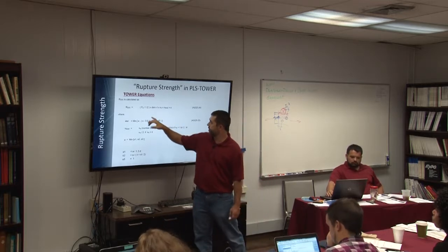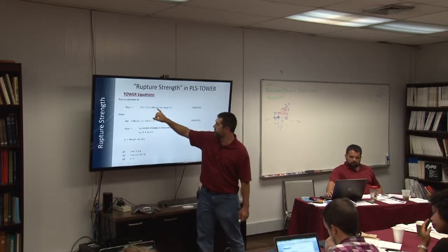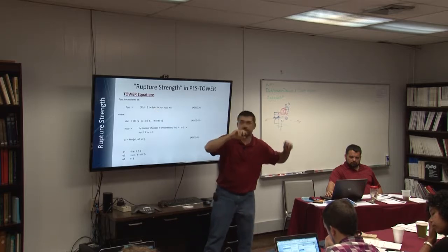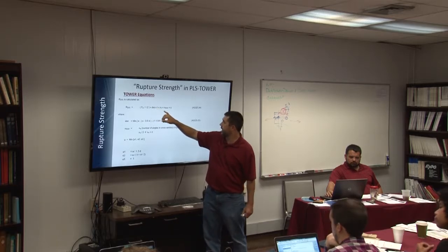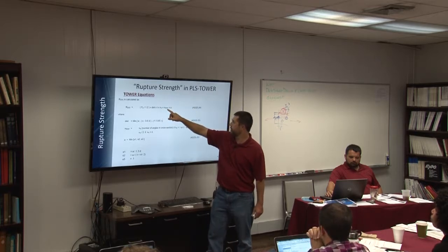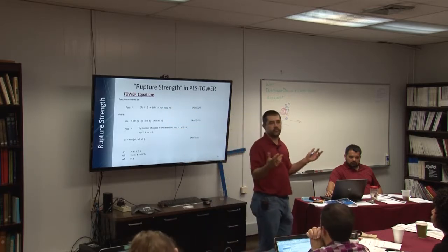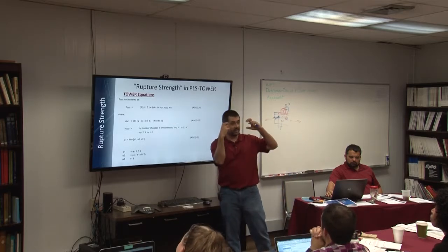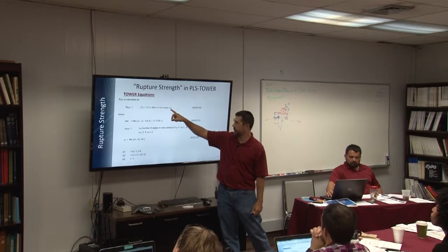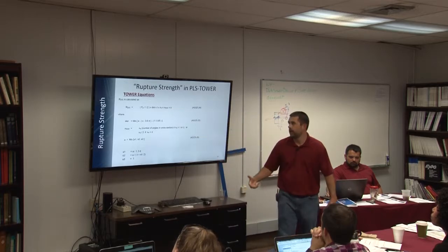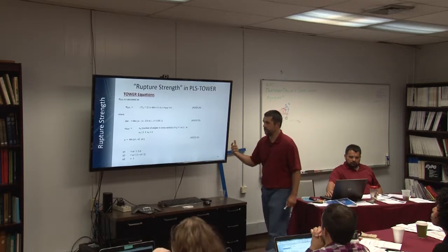So what they've done, right, is you've got FU over 1.2 times the thickness times, we're going to call it distance for now. And then they've got basically the number of bolts, the number of bearing areas. So if you had a bolt in double shear, you'd have 2 bearing areas on either side of your member, times basically alpha, which is a reduction factor. Okay? And hopefully you'll be able to see how all this comes together.